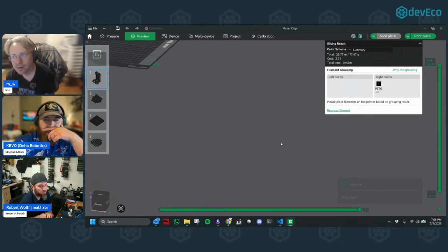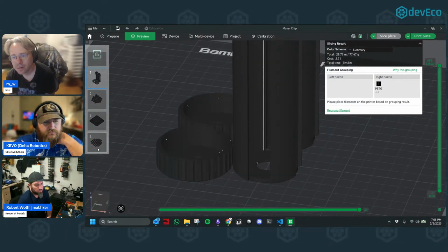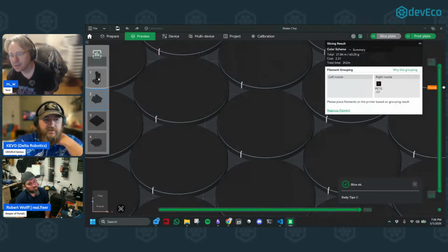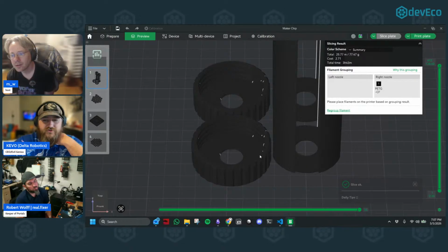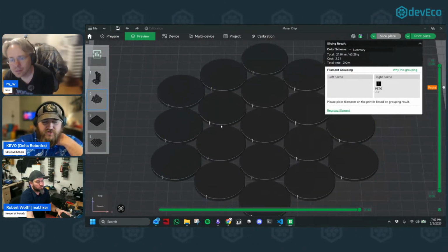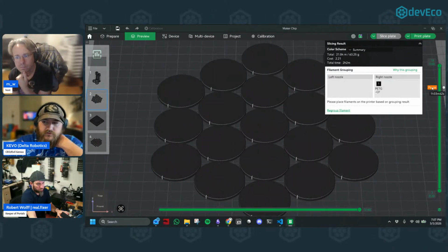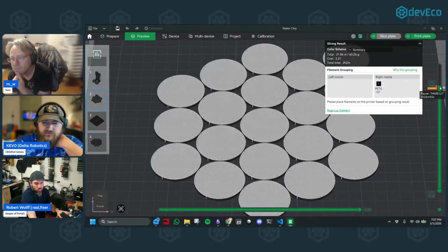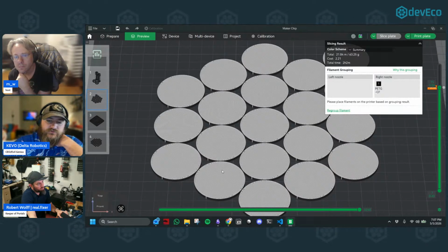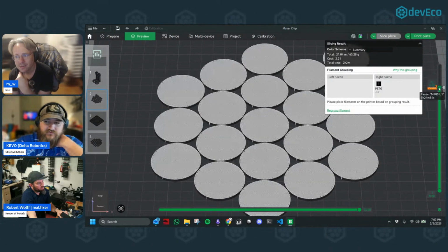Okay, it's far away. There you go. So this is not one of the chips. Of course, it's not. Looks like a stack or a holder. It's actually a holder. I've got a new version I'm working on. I'll talk about that later. But you have your chip here, and let's say this is a batch, so you're making a bunch of them. I've got a pause set up here so that at this layer specifically, the printer stops, notifies me, and I can add NFC stickers to each one of these, and then continue printing.